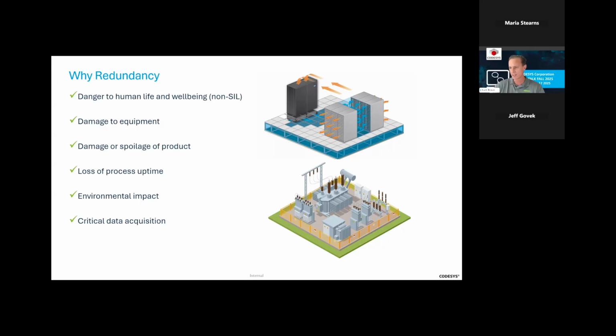Also, anytime there's an uptime concern where you need high availability, having a redundant controller could mitigate some of those issues and allow for higher uptime. And if you're doing any kind of data acquisition where there are regulatory requirements to maintain data collection over a certain period of time, having a redundant controller to help with that collection of the data is also beneficial.